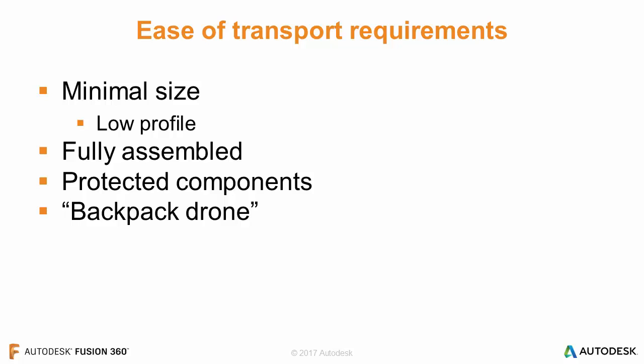So knowing the size of the motors, the size of the props, the batteries and all the other components, it's really going to drive the overall shape. But we know that we can keep it as small as possible while fitting into all those different requirements. One thing that is a big variable is the height of our device. We want to keep it as low profile as possible.